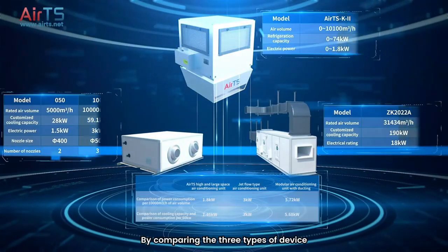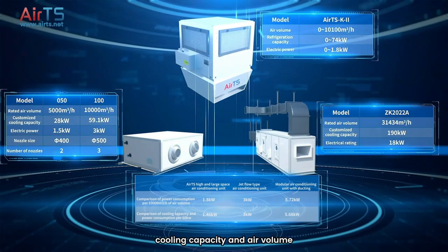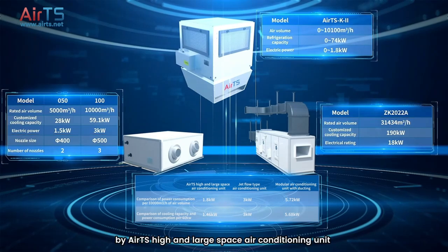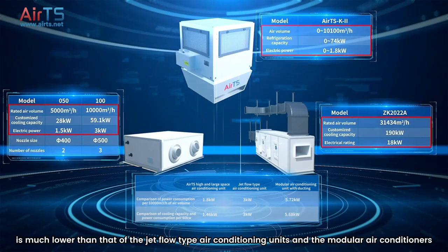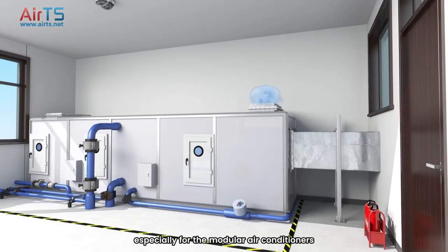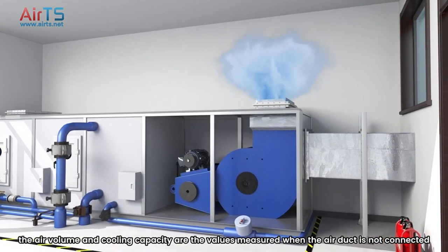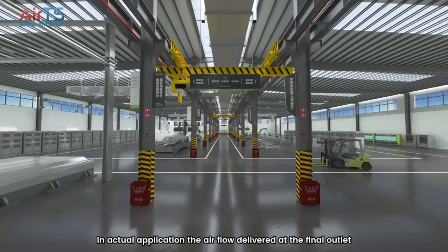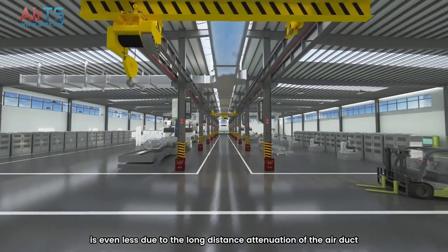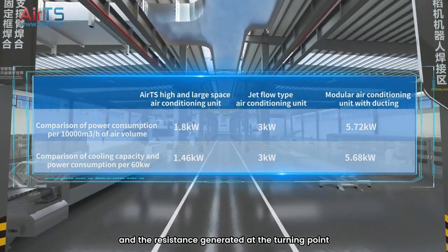By comparing the three types of device, it can be clearly seen that under the conditions of obtaining the same cooling capacity and air volume, the electric energy consumed by AirTS high and large space air conditioning unit is much lower than that of the jet flow type air conditioning units and the modular air conditioners. Especially for the modular air conditioners, the air volume and cooling capacity are the values measured when the air duct is not connected. In actual application, the airflow delivered at the final outlet is even less due to the long-distance attenuation of the air duct and the resistance generated at the turning point.